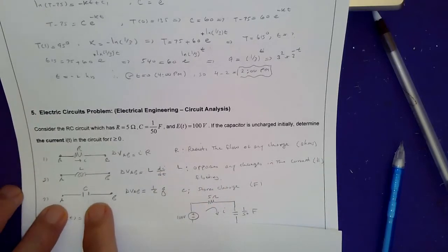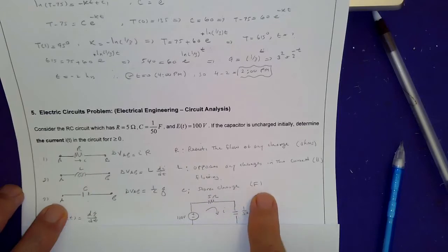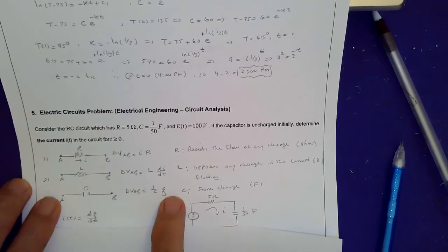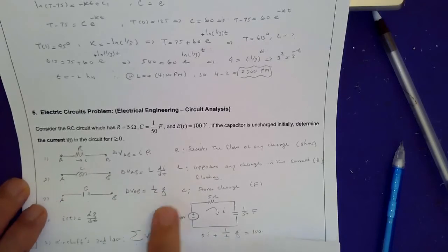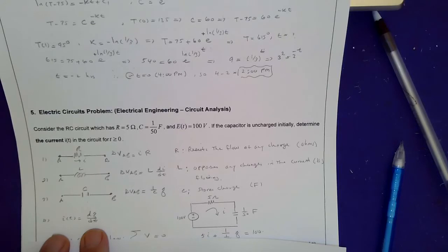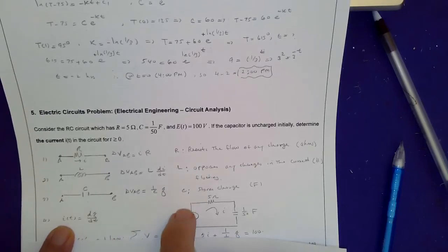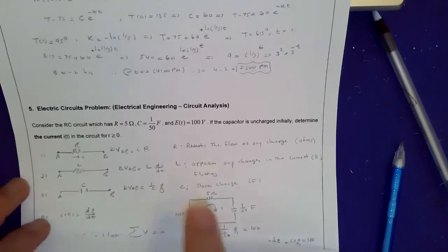This is a capacitor. A capacitor stores charge and its unit is the farad. The amount of voltage drop across a capacitor is 1/C times Q. Q is what? It is the electric charge, and this is how it's related to the current. The current I is the rate of change of electric charge with respect to what? Time. So in other words, this would be like coulombs per second, which is I, and the unit for I is also known as the ampere.